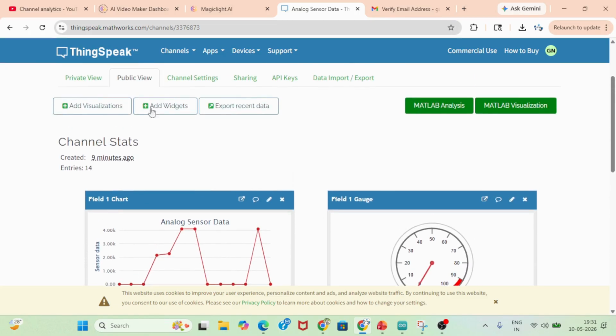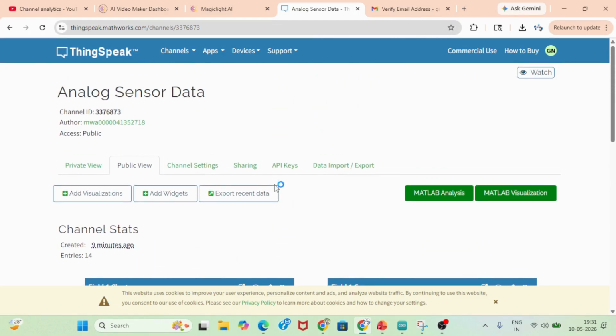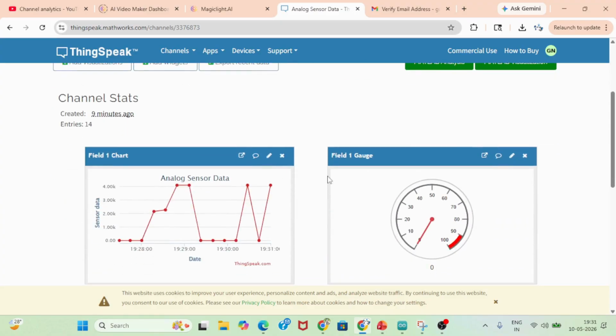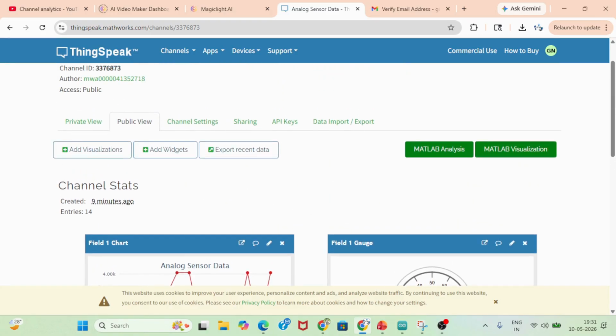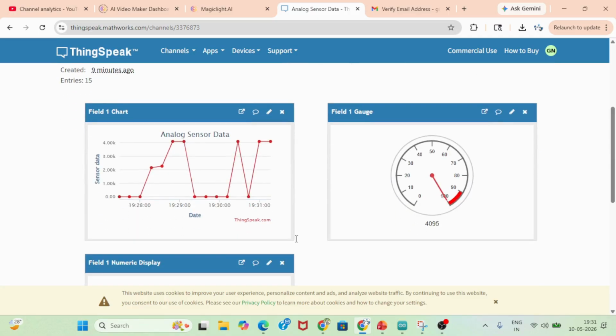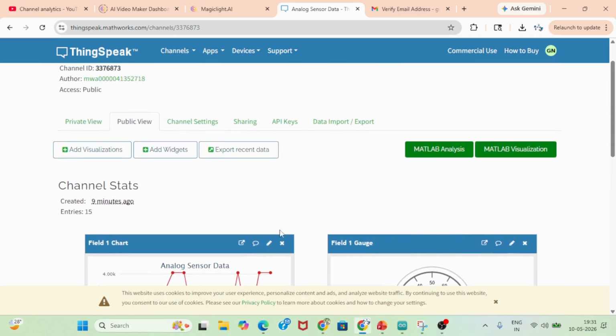Based on the sensor real time you can access this, and you can also access these things in your mobile. You just have to log in with your credentials, like your user ID and password. If you log in, then after that you can check the data anywhere. And remember one thing, for the ESP32 you have to give a proper internet connection. If your internet is slow, it will take some time for the upload.